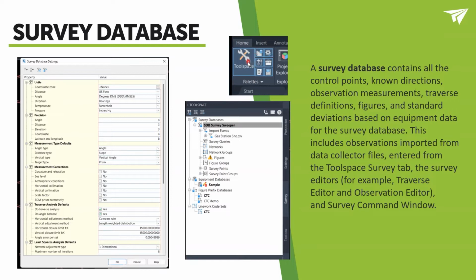This is going to be in the Home tab. In the Home tab, we have our tool space highlighted, but just make sure that we have this survey button highlighted as well in blue. That gives us access to our survey tab within our tool space and gives us all of the tools that we can work with in processing our data through our survey database, as well as our survey figures and our code sets.